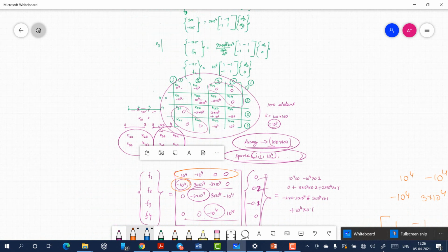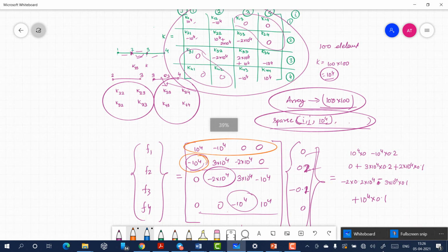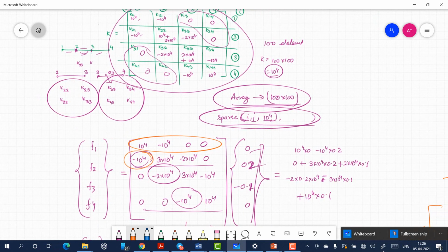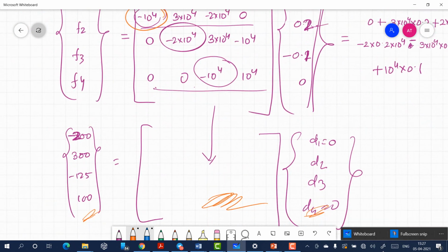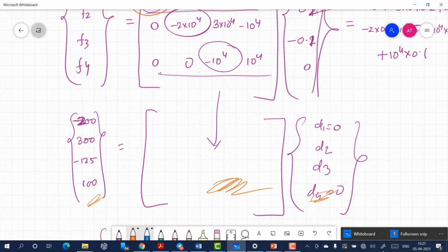Okay. So that is the process anyway. So this is a non-invertible matrix. It should be an invertible matrix. If it is non-invertible, if it is singular, it means that you will not have a solution. So that means there will be no convergence. Okay. So that's an error, but that's how you do it. That's how you find out the values of forces and displacements.